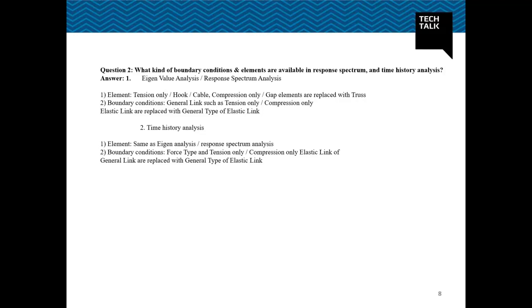Moving load provides a relieving effect in our compression only springs. So if we don't consider that relieving effect, we are overestimating the forces that may arise in our compression only springs. Hence, for a more economical design, it is recommended to not use tension only springs in moving load analysis.